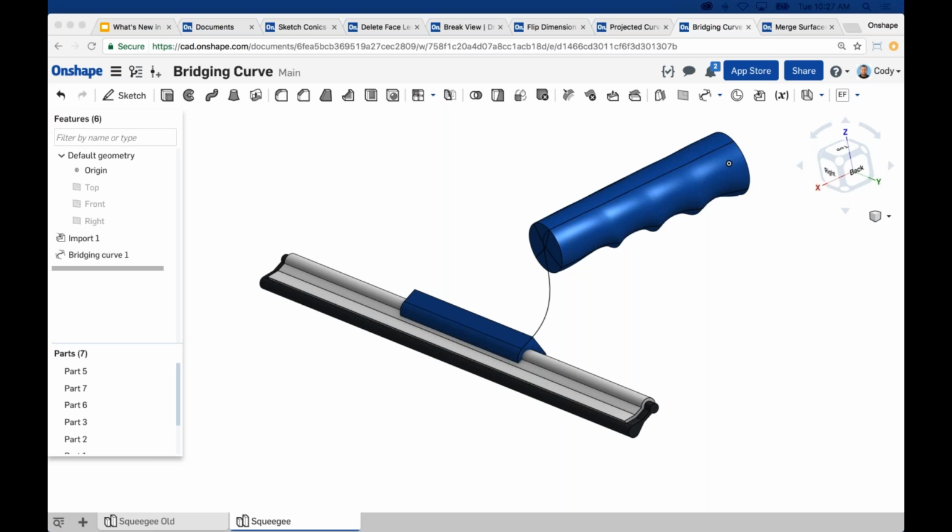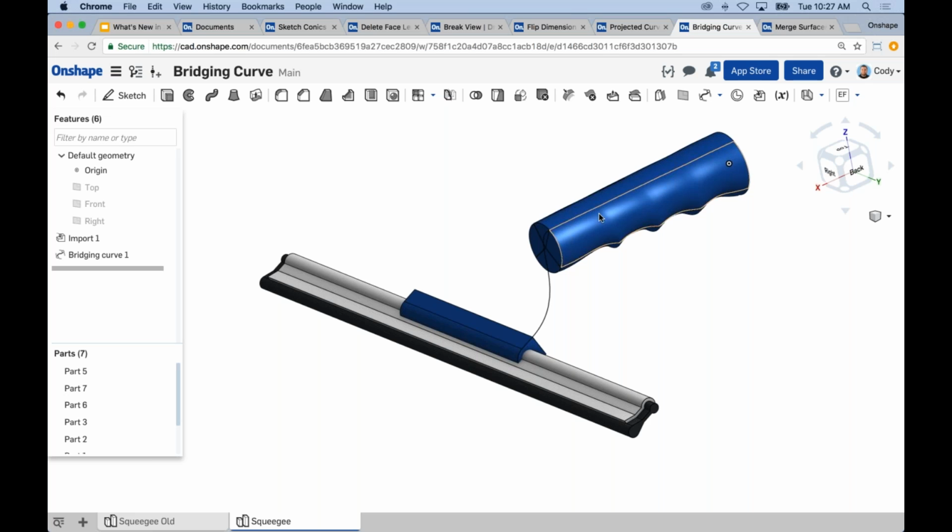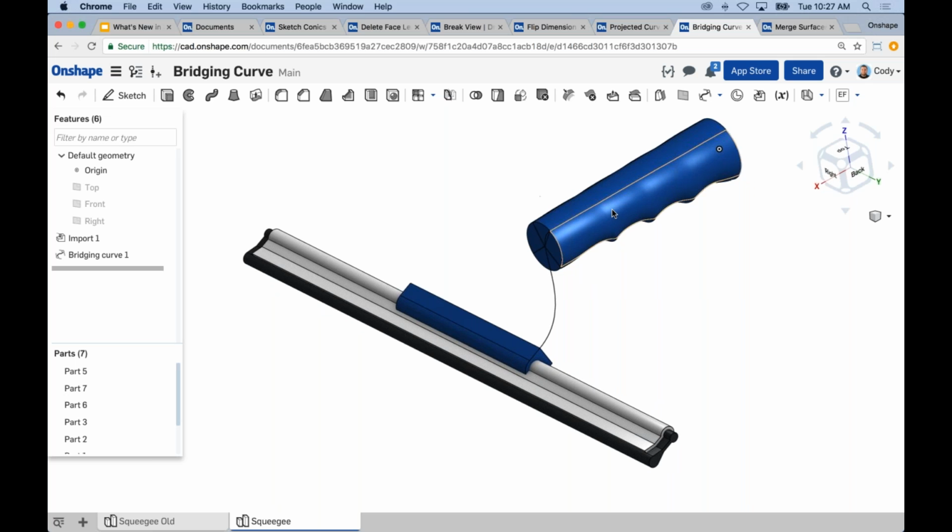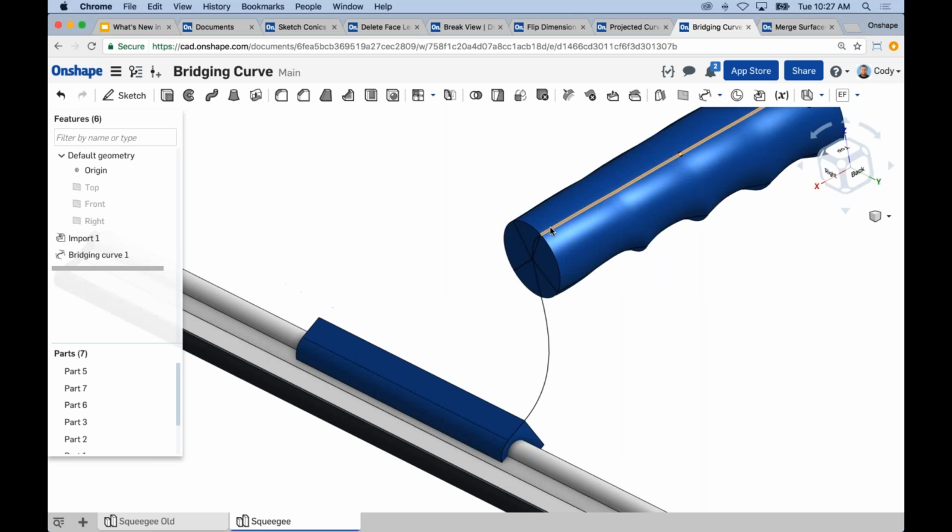How do you create the lines along the handle that you used for tangency? I use split just to split the model up. So I extruded surfaces and split it. That's one technique. You can always, of course, later merge everything back together. That gives you your lines. It's up to you. An edge is a very simple way to define tangency with another part.